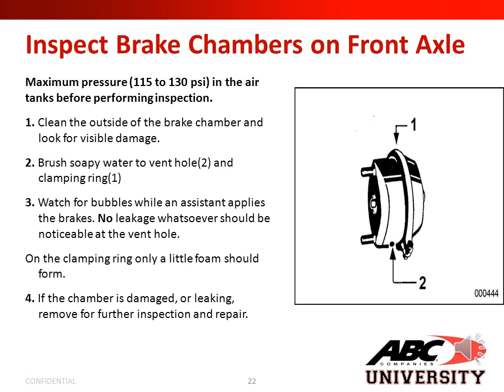No leakage whatsoever should be noticeable at the vent hole. On the clamping ring, only a little foam should be formed. If the chamber is damaged or leaking, remove for further inspection and repair or replace as needed.